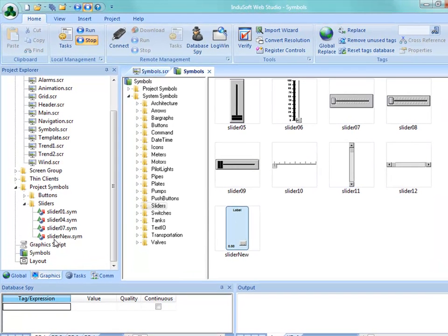If you create a bunch of individual symbols, you can go into your project, copy all those symbol files all at once, the .sym files, and just go paste them into your system symbols folder. So there's nothing special about the right-click mechanism, and sometimes if you're creating a lot, it's a little bit easier to go into your project symbols, copy them, go back into the install folder and paste them if you're doing a lot all at once.